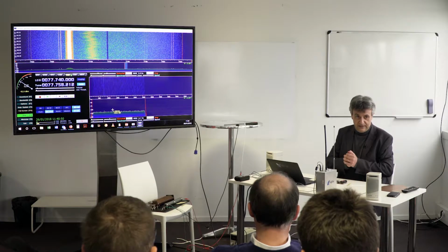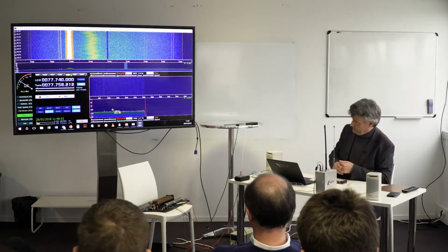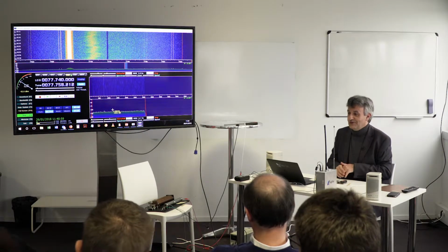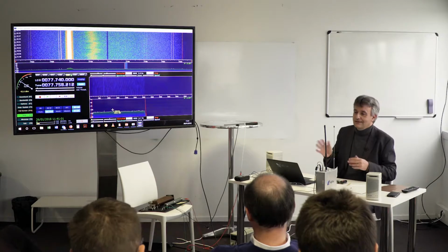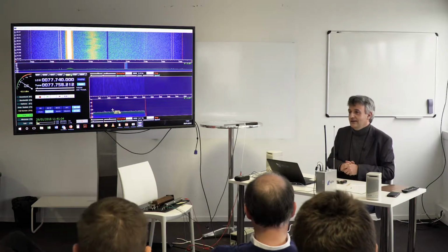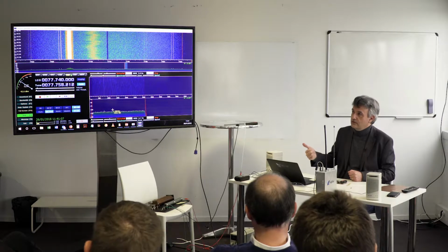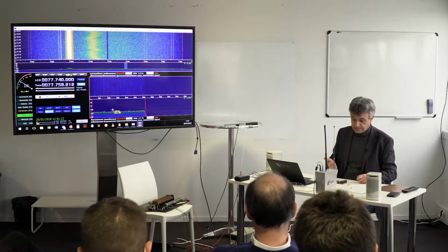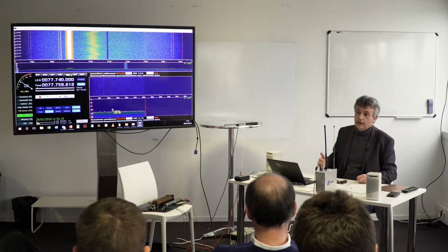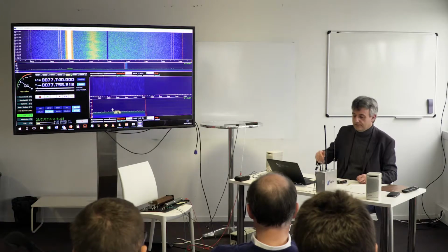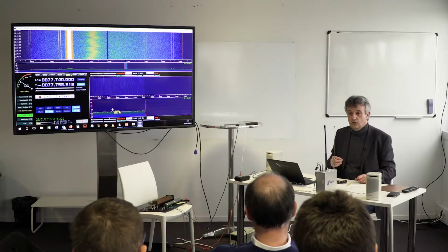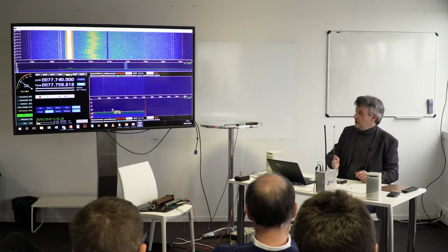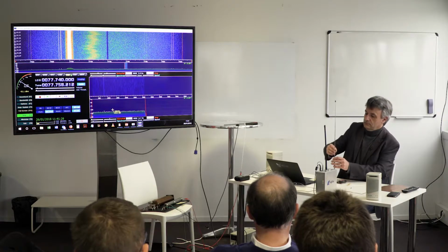By the way, what is the wavelength at 77 megahertz? You take your calculator, but it's the 4 meter band. We are within the 4 meter band. 100 megahertz is 3 meters, 50 megahertz would be 6 meters, and 77 is in the range of 4 meters. So basically, a quarter wave would be 1 meter. Okay, we are far from 1 meter. Maybe we can approach the 1 meter.